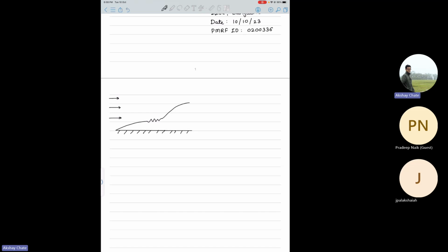There is a reason behind it, there is a story. Basically, you start with inviscid flow because that is easy to solve. Viscosity effects are difficult to incorporate. So let's say this is your free stream velocity, which is u infinity, and this is 0 comma 0, your origin. This is your y coordinate and this is your x coordinate. This is a typical setup, a flat plate, and in this highlighted region, they assume it as an inviscid region.